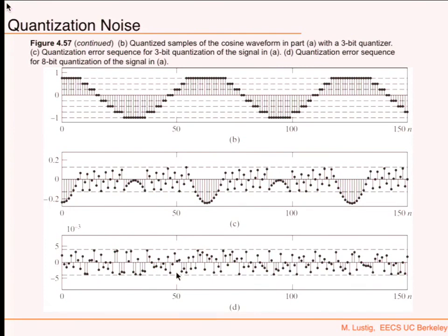Yes? So you said that it's a good model when the signal changes rapidly? It does change rapidly with respect to your sampling, and the quantization steps are small. But don't we also want to sample really fast? If it changes really slowly and you sample really fast, that's a problem, because then you'll get errors that look like this.